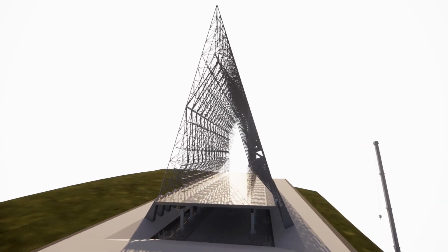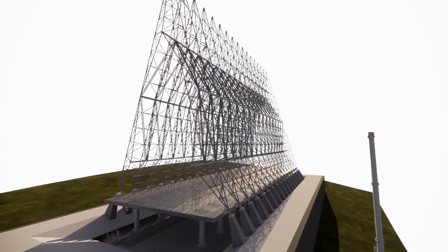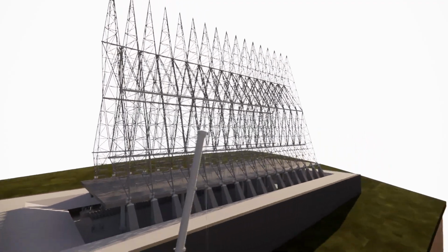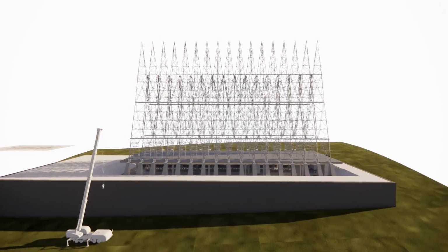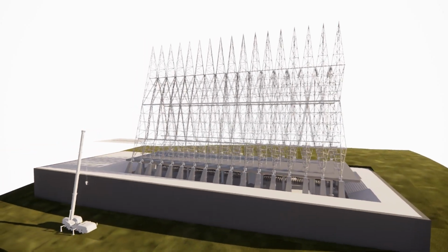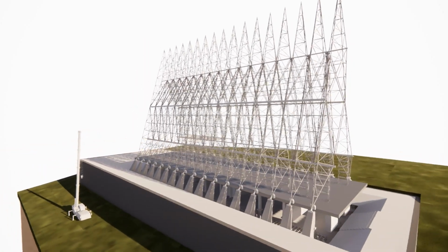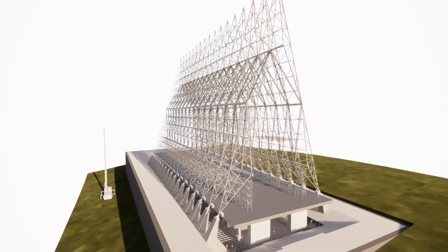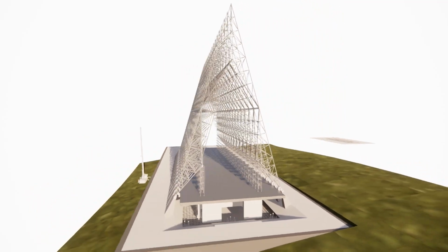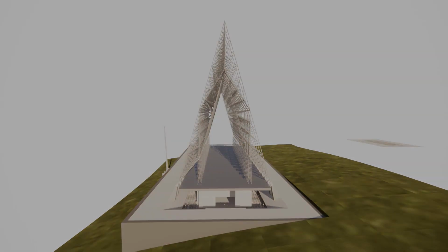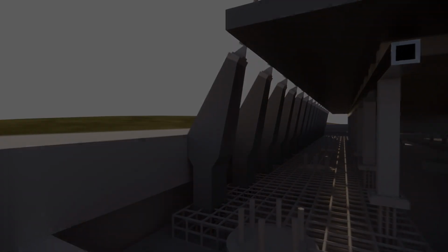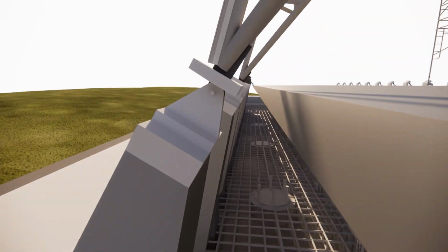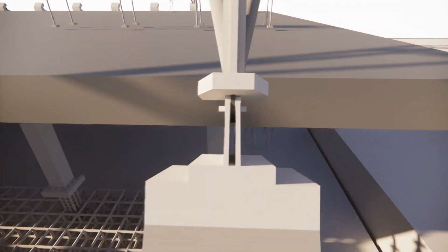The roof structure is primarily made of steel and its load is transmitted down the slope. Reflecting these characteristics, we have constructed a foundation specifically for the roof. The roof part consists of 17 repetitions of the same shaped spire, and we will take one of them for examination. These spires are grounded at a particular angle, supported by a base of such shape through steel hinges.